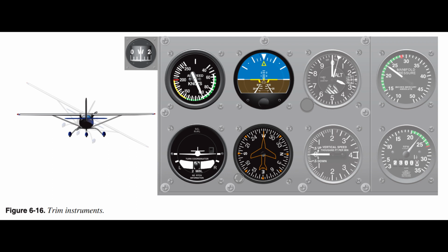3. Using balanced power or thrust when possible to aid in maintaining coordinated flight. Changes in attitude, power, or configuration may require trim adjustments. Use of trim alone to establish a change in aircraft attitude usually results in erratic aircraft control. Smooth and precise attitude changes are best attained by a combination of control pressures and subsequent trim adjustments. The trim controls are aids to smooth aircraft control.